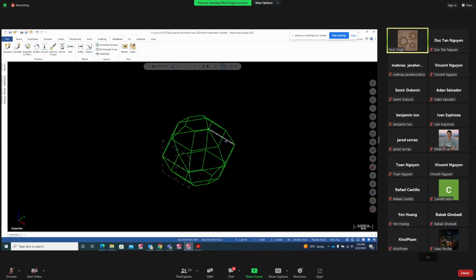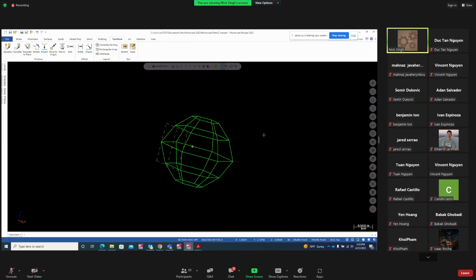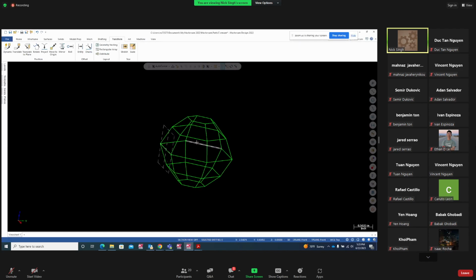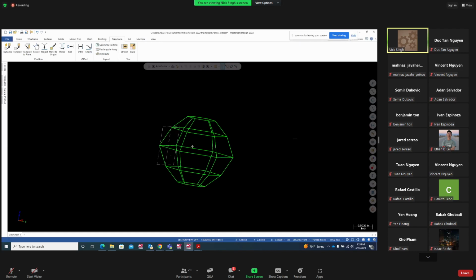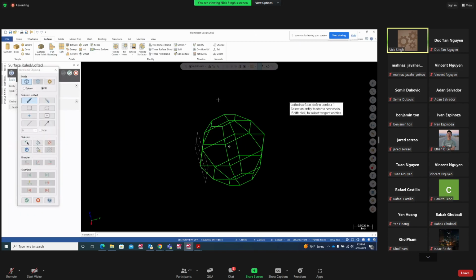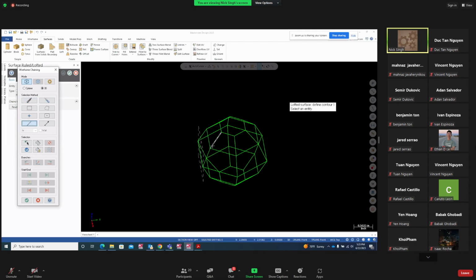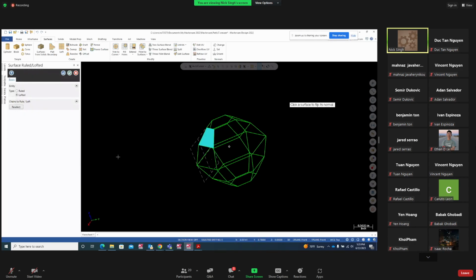But I need the surfaces on all this. There are my surfaces. So to create the surfaces, I can use, here, go to surfaces, I can use loft. And with loft, you can create a surface on each flat. So I can go single, they're all single. This is my first one. I can go first, and then I can use my second and apply here, okay. And there's my surface.